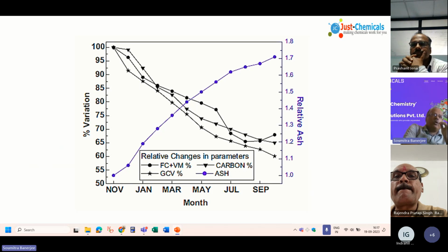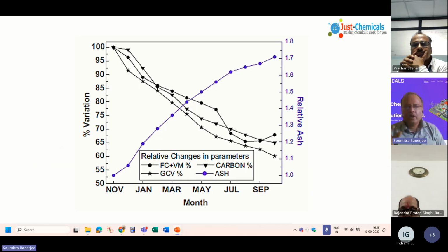If you're keeping the coal for a longer duration in storage, and that also in an open storage, now there are closed covered storages available. But anyway, in the covered storage also, VM will go up and will be in the top of the cover, and as soon as you remove the coal, you still lose the VM and the carbon associated with the VM. So this is the first slide which I'm showing you, and this is the gist of the whole presentation on storage.